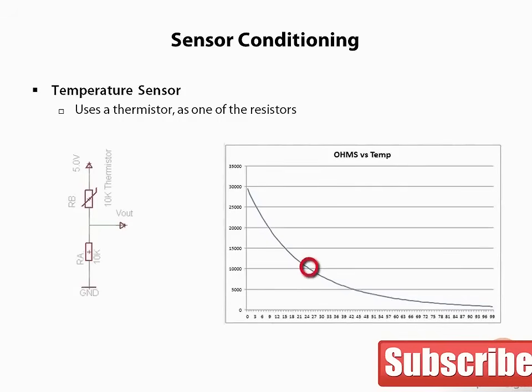degrees C. The curve is nonlinear, so in order to interpret this data, we would need to build a table or do some form of curve fitting in our process to relate the thermistor's changing value with temperature. But first, we have to get the changing resistance values into something our process can use, which is changing voltage values.